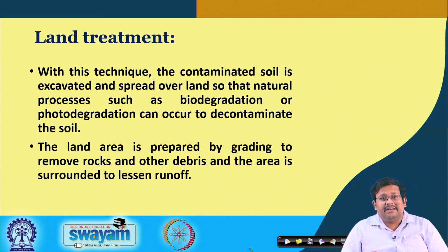Now, land treatment is a technique where the contaminated soil is excavated and sprayed over the land, so that natural processes such as biodegradation or photodegradation can occur to decontaminate the soil. So, basically here the soil is excavated and then kept over the surface, so that it can provide the required area for carrying out the bioremediation process as well as other decontamination processes.